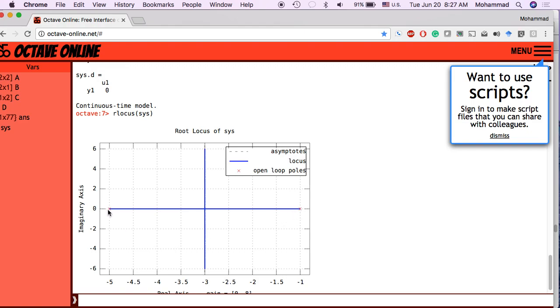The one that is located at -5, for any non-zero value of k, they start going to two other poles located elsewhere, not at -1, at -5, closer to this -3. So at some value, which I think we determined was 0.8, if I'm not mistaken, at some value for k, the two poles would be identical and they would be both located at -3.